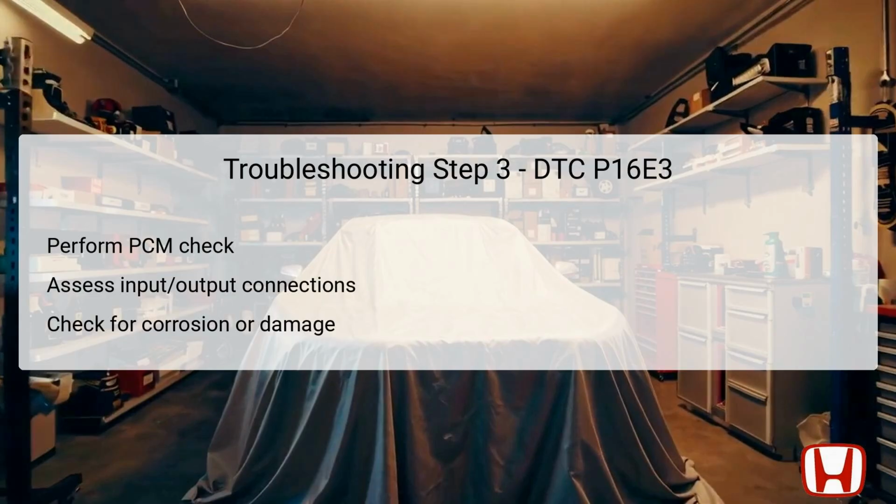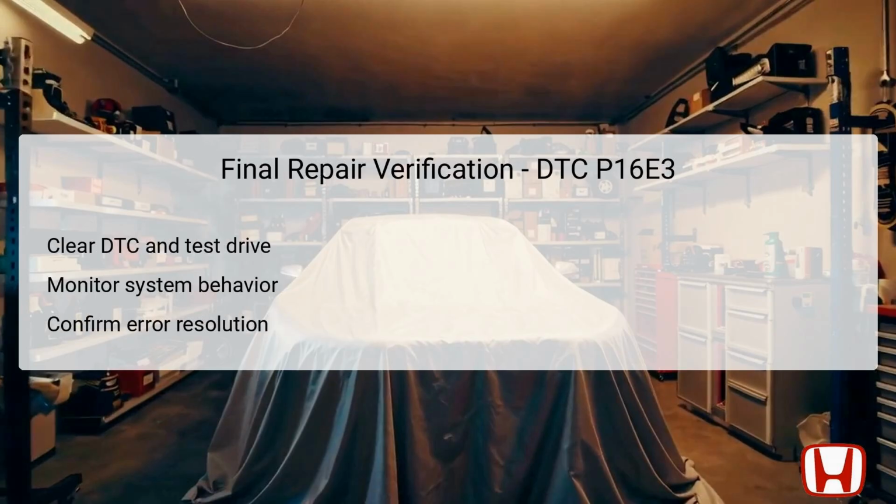the P16E3 error. Once repairs have been completed, it's essential to perform a final verification to ensure that the P16E3 error has been resolved successfully. Start by clearing the diagnostic trouble codes from the PCM. Then, take the vehicle for a test drive under various scenarios to confirm the effectiveness of the repairs.